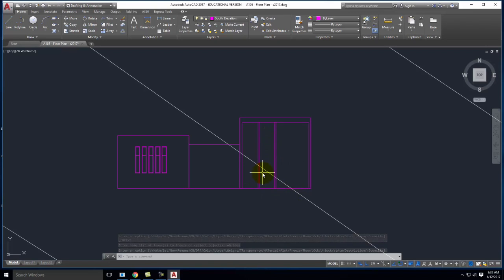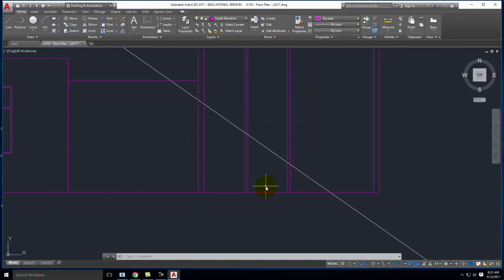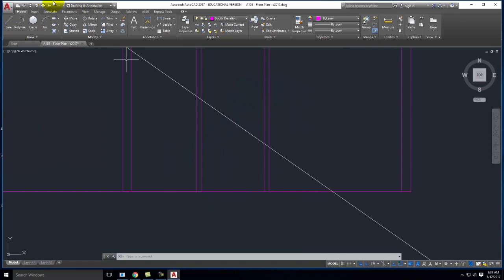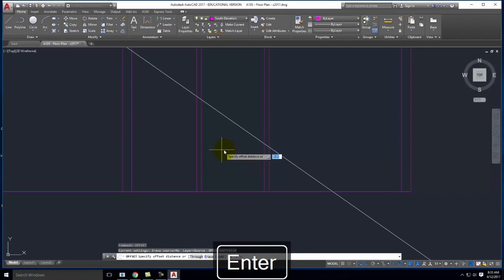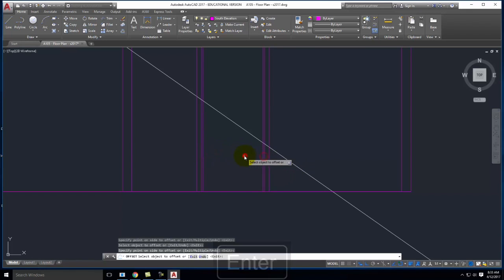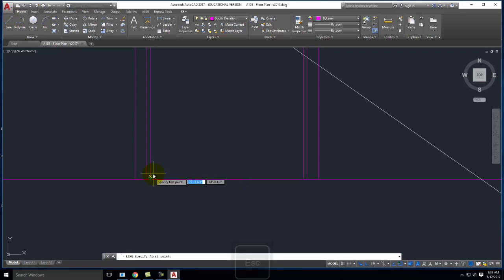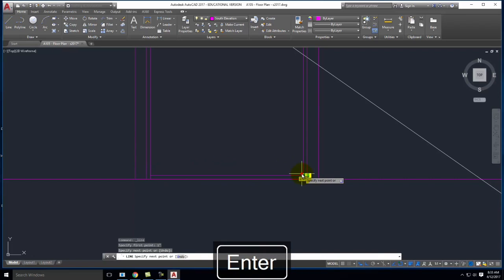There's probably a little bit more to it. There's probably window frames and that sort of thing. So let me keep going a bit. I'm just going to draw this window pane, and then I'll copy it to the other places. So let's assume that there's going to be a window frame. So let me use an offset, and we'll do 1 inch again. And we'll offset each side of the window. We need a line that goes 1 inch up here and across.